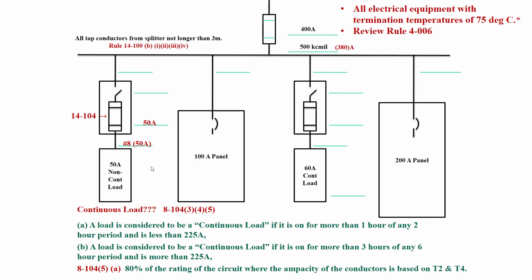Now for the 50 amp fuse, I need to size what size of disconnect to purchase or to install for that 50 amp fuse. If you recall back from the previous slide, the ranges for our fuse holders were 30 amp, and then it went to 60 amp, then to 100 amp. So the 60 amp would work just fine. So we'd purchase a 60 amp disconnect. Okay, so we have sized the whole branch here with the fuse as well as the disconnect.